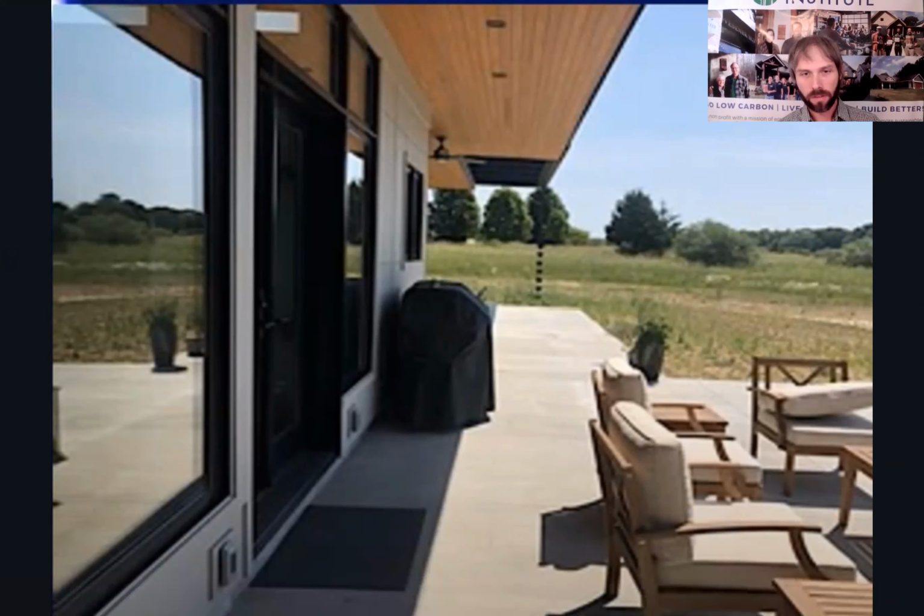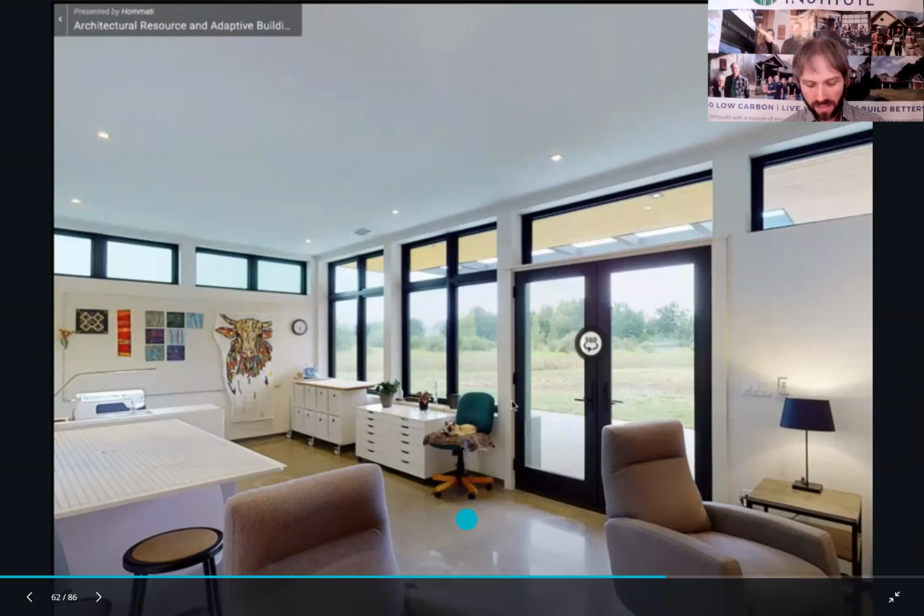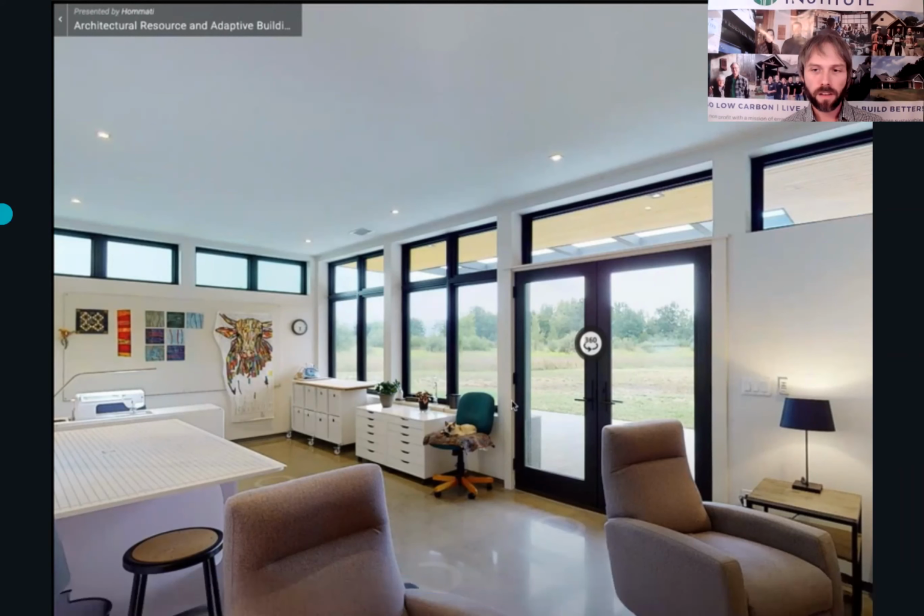The patio, I think, is reflective too. So you're really just stopping that house from overheating in the summertime. And then in the wintertime, the sun will dip real low into the horizon there. It'll come in these nice south-facing windows and it'll hit this concrete floor or hardwood floor, whatever it is, and it will absorb that heat and then radiate that heat off into the night, providing totally free energy for your client, assuming you've designed it appropriately.